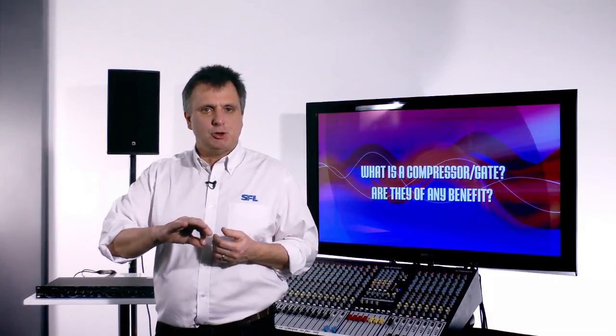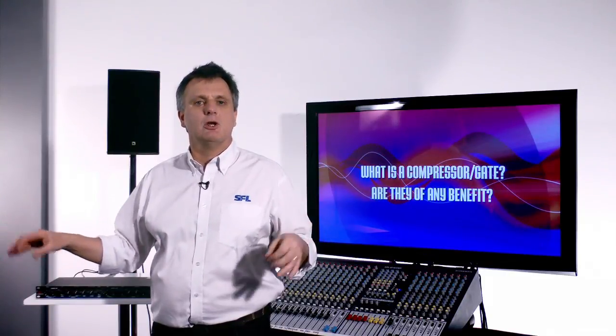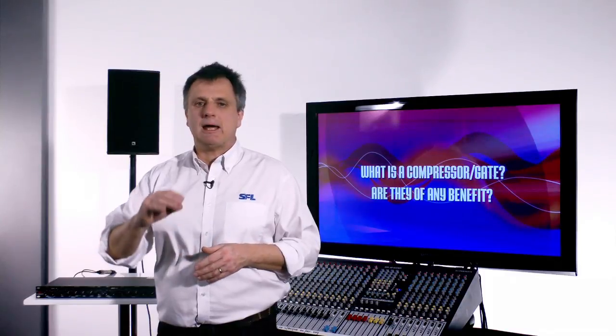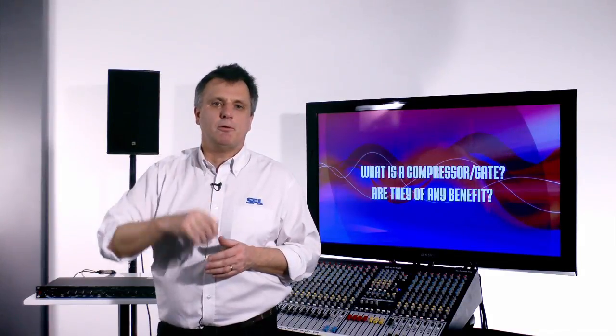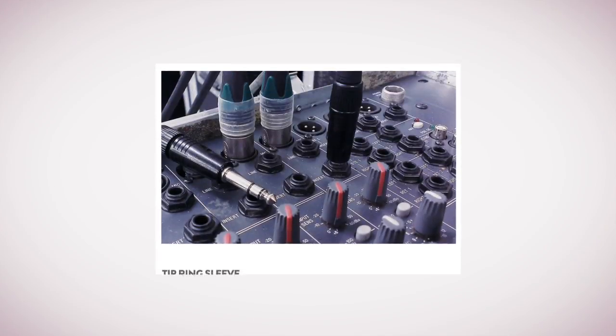In an earlier module, we talked about gain structure and the path of a signal through a mixing desk. We realized that we go from microphone to mixing desk, and there we hit the microphone preamplifier. Here we apply some electronic gain. It's the main knob at the top of the channel strip. Really then the next thing that happens, we have an insert point within the mixing desk.